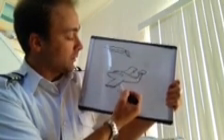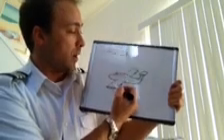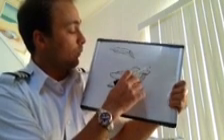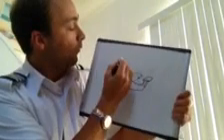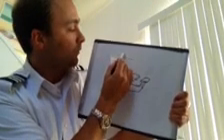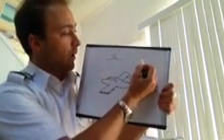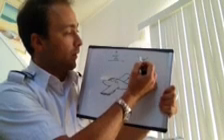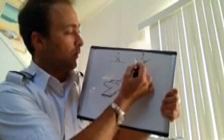The aileron raised into the relative wind, with a lowered camber and a lowered angle of attack, is going to cause a drop. And this is going to change our component of lift on the aircraft. What does that mean? If we have an aircraft flying straight and level, its lift is generated vertically. If we have an aircraft in a bank, it now has another component of lift. It has a vertical component of lift and a horizontal component of lift.